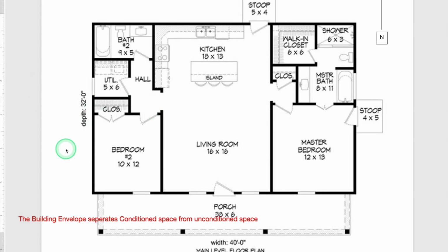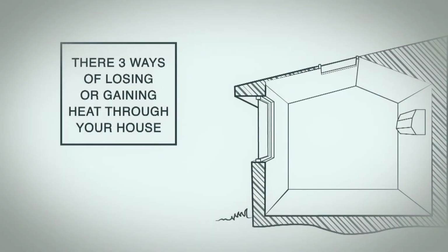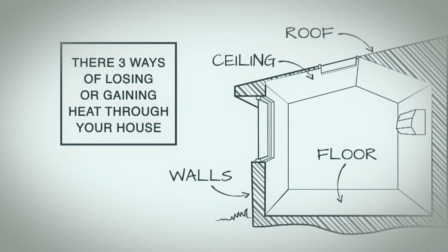And how does it do that? Well, they use construction material that's supposed to resist heat transfer. Now, heat transfer is going to, like we've said, take place, but the material is going to resist it. So R value stands for the resistance to heat. U value stands for the conducting of heat.